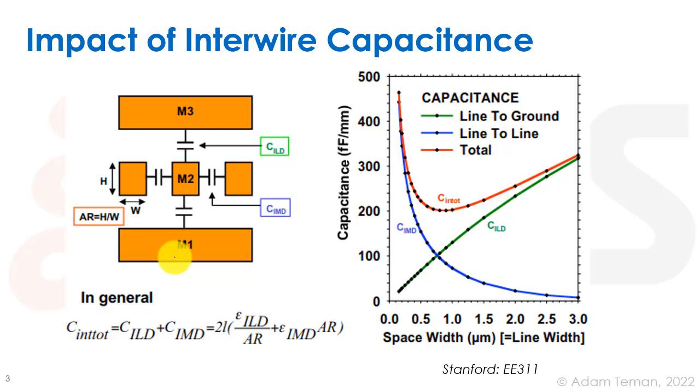And then we discussed the fact that if this was the parallel plate capacitance to ground, that we had fringing capacitance. And that was maybe because the wires were much smaller, they got thinner, and the other thing is they may have gotten higher. But really, since we've had many more metal layers, and our wires do get much more tall and thin, then we get coupling capacitance, which becomes really critical and bad.